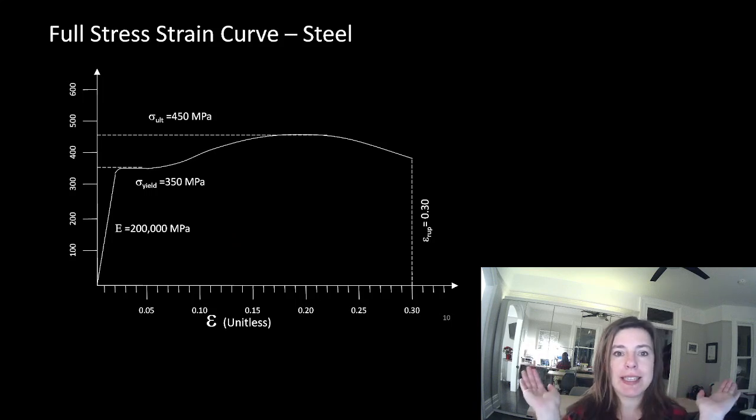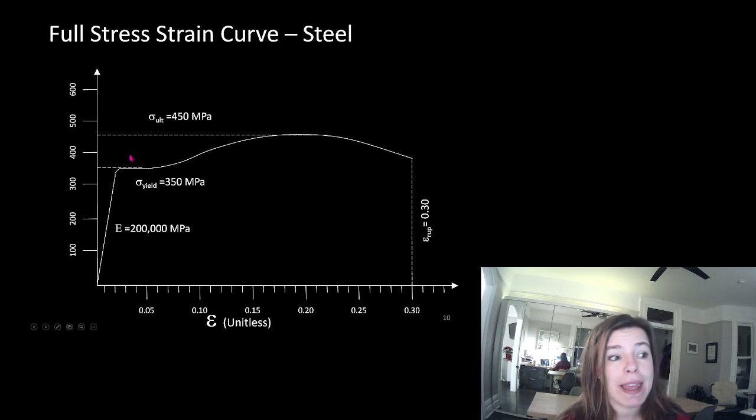If you've got a steel member that's bent all the way in half, we might call that not a deflection problem, but a strength problem. Well, that's because we've exceeded the strength yielding limit that we've defined as our life safety criteria.